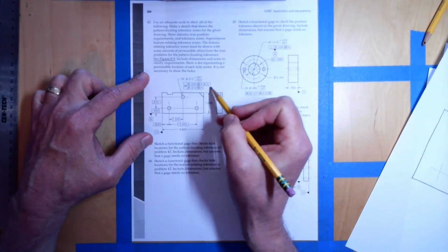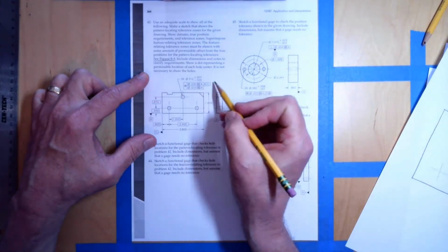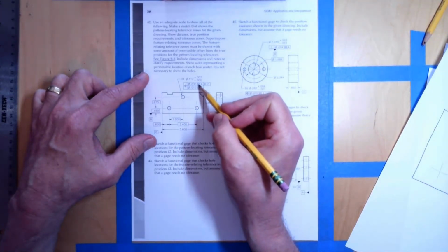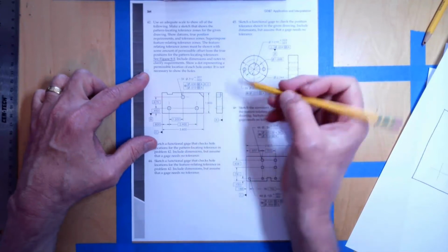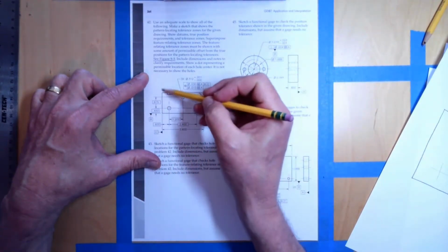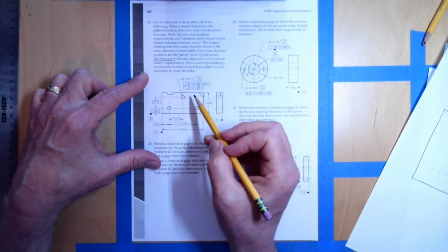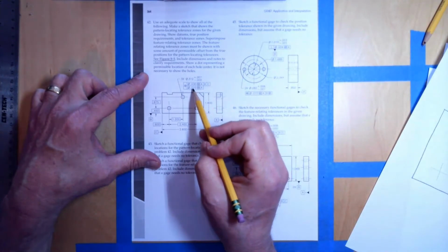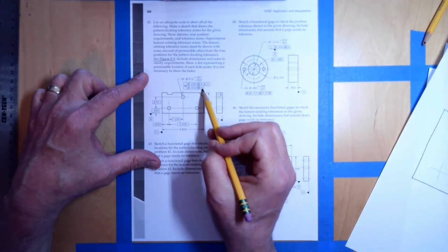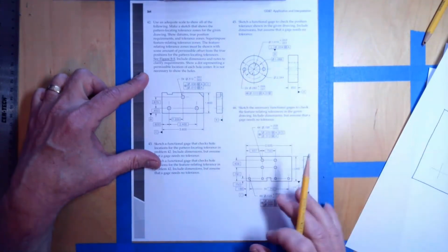And then we have a composite positional tolerance where the upper segment, the pattern locating tolerance zone, is a .030 tolerance zone at MMC relative to A, B, and C. Here's A, here's B, and here's C. And then the lower segment, or the feature locating tolerance zone framework, is a .010 diameter at MMC relative to A, so oriented relative to A. Okay, so let's see how we're going to do this.